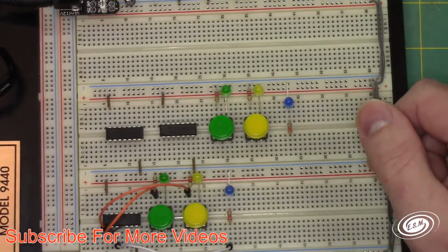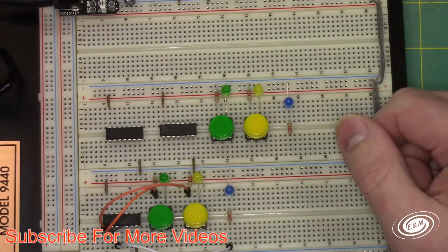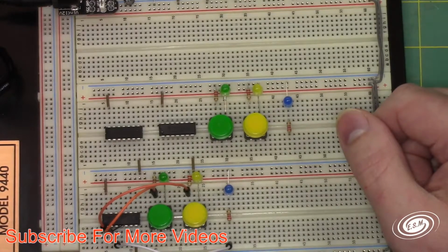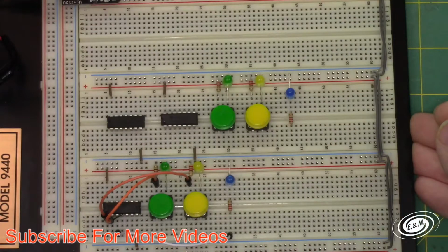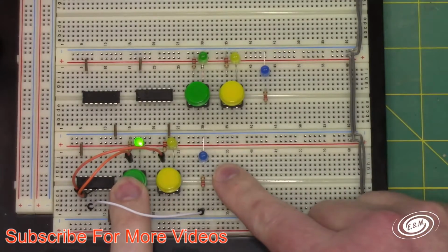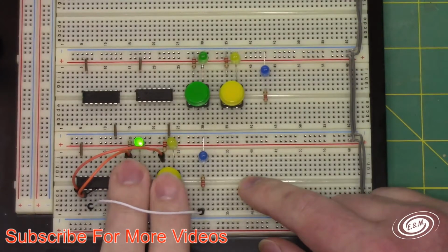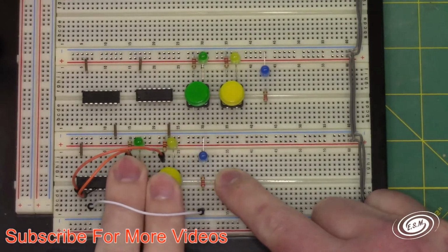So let's get power from the power supply here. I might have to fiddle with it, because I believe I was putting out 5 volts. Yeah, I got to turn it up to 9. I have a voltage regulator that powers the breadboard, and it needs 9 volts. So 9 to 12 volts. So press 1, the input lights, but the output does not light. Press the other, same thing. So neither one. If I press them both, the output lights. So there's my AND gate right there. So that's an AND gate.